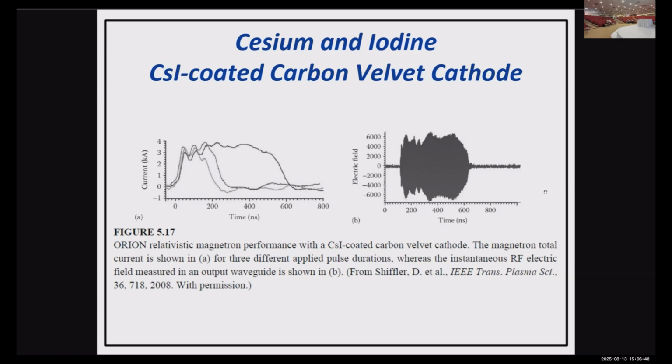But having this, you have to think about the plasma. What's going to happen to the electron? You're going to have what they call electron compression or decompression. Your electrons are not going to go back in a straight line. They're going to go away from the slow wave structure. So yes, you're going to lose the electron electromagnetic wave interaction.